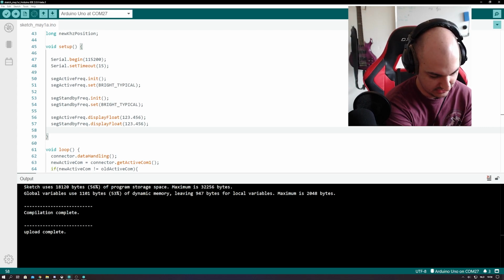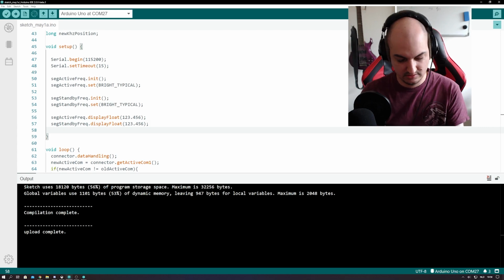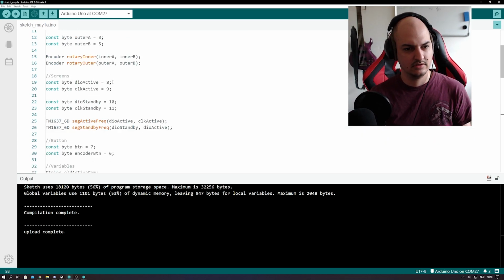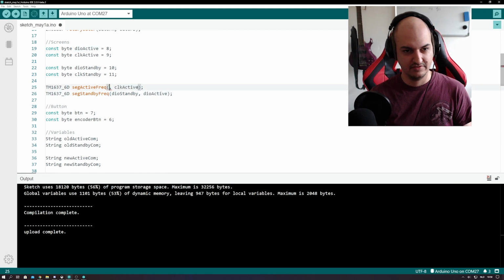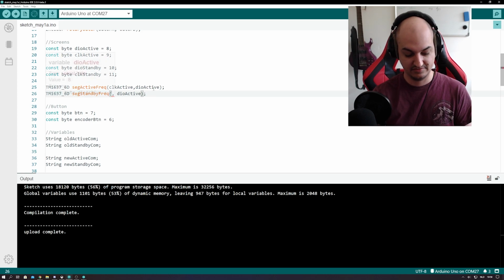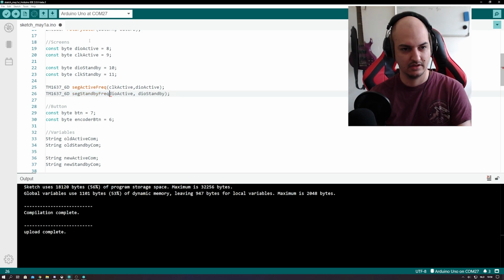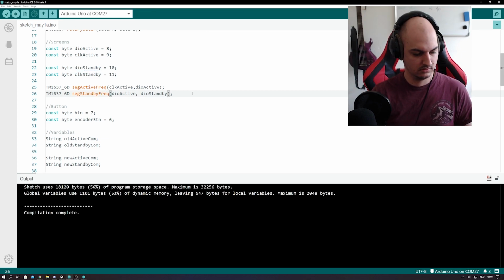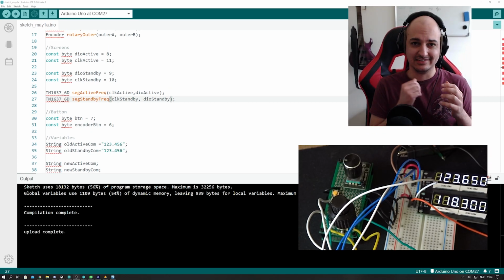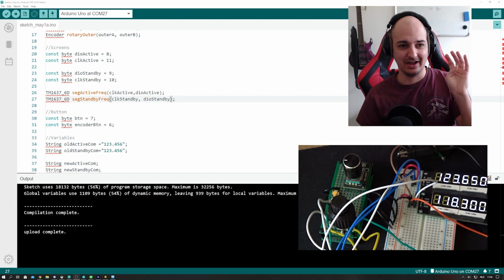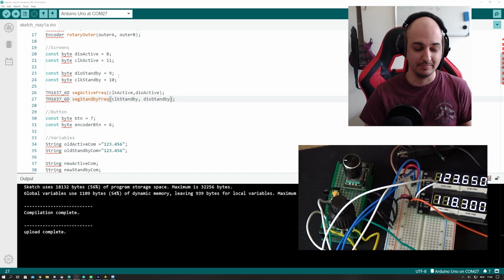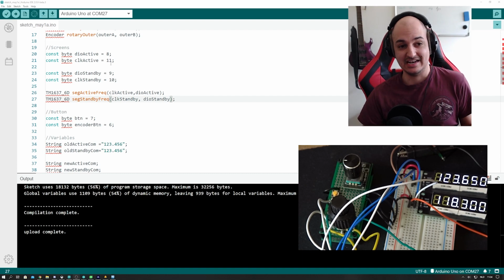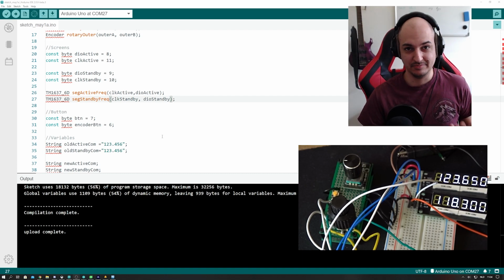I have a feeling that, no, we're going to do it properly. Here we go. I have a feeling that it will take the CLK first and then the diode, so we mix these up. So let's see if that is actually the case. So I messed up the most basic step, and that's to check the pins. I had 8, 9, 10, and 11, but apparently I messed up and put them in 8, 11, and 9, and 10. So I could debug whatever I wanted.